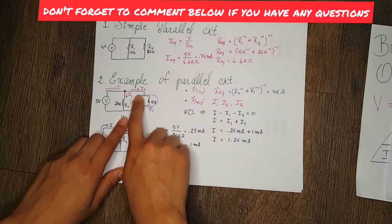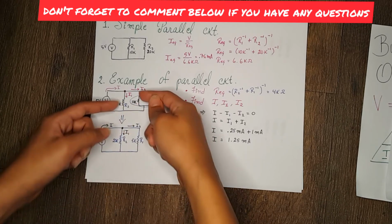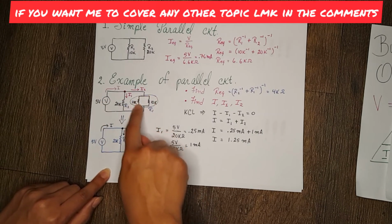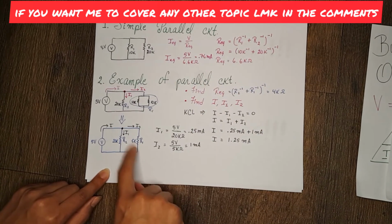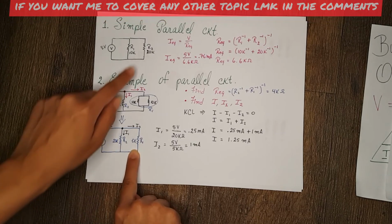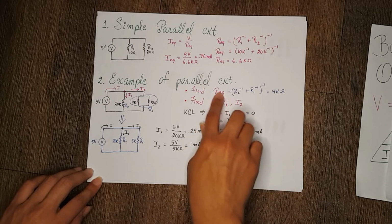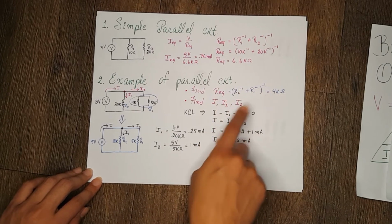So now we can take these 2 parallel resistors and make them one resistor. So right here we're going to have 5 volts, 20k, and now this combined would be 5k. So we have 20k, 5k, and now we're basically at the same circuit that we had before. And now we can find our equivalent just like before, which is equal to 4 kilo ohms.